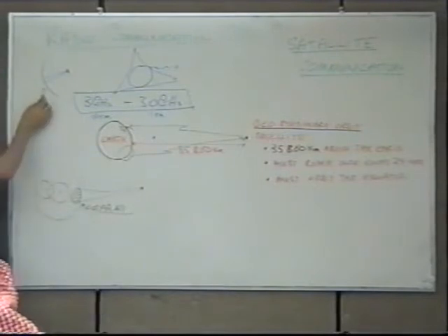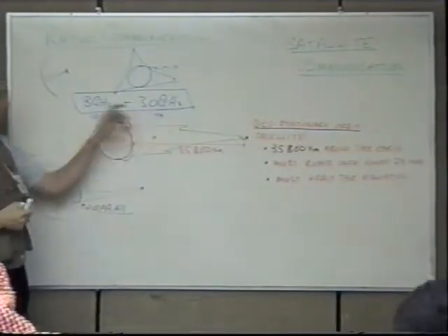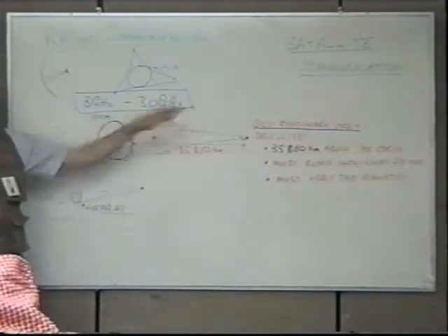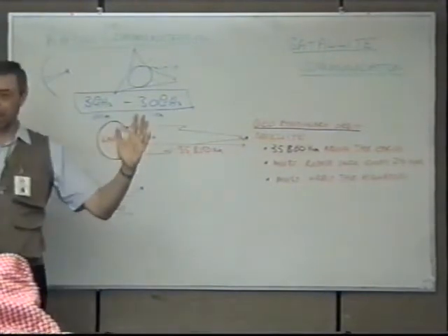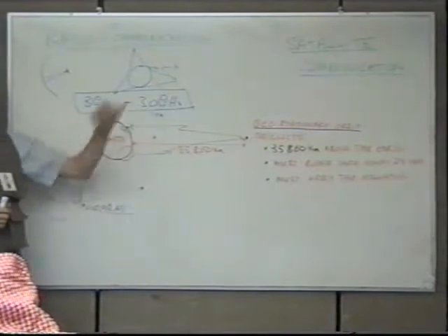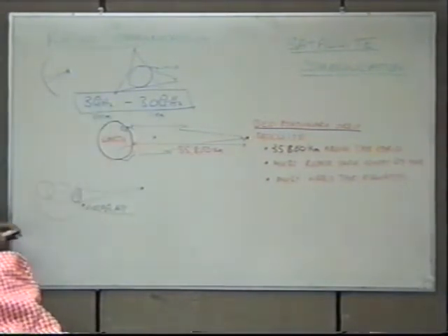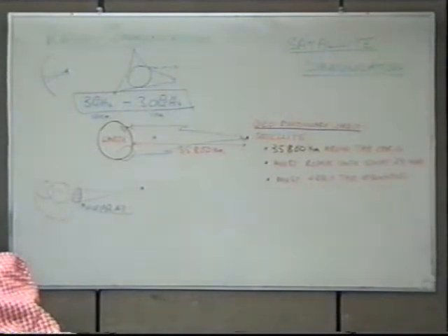In fact, this is the reason why we can use dishes, because of such short wavelengths. And of course, one advantage of using these frequencies is you've got a lot of bandwidth, a wide bandwidth. Imagine how many telephone channels you can fit in if you were using frequency division multiplexing. How many telephone channels you can fit in there? It'd be thousands and thousands of telephone channels.